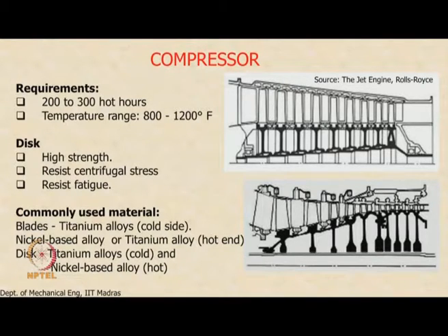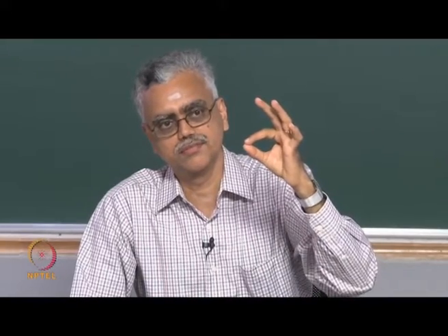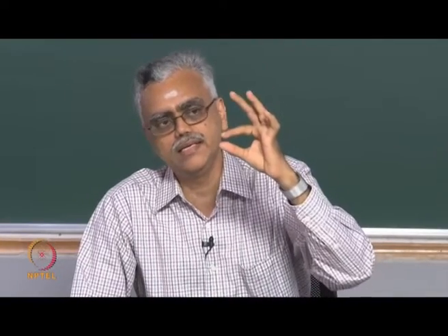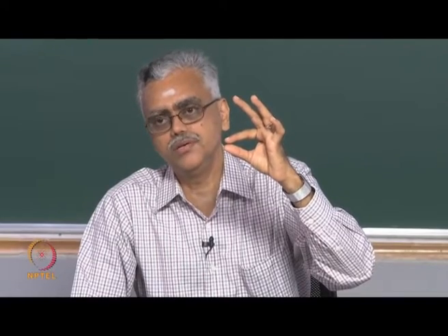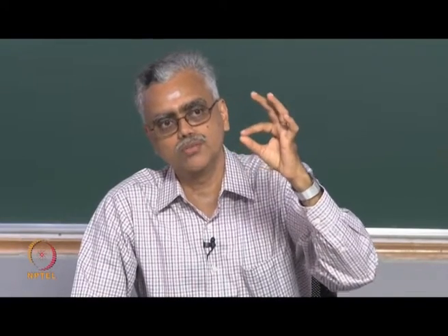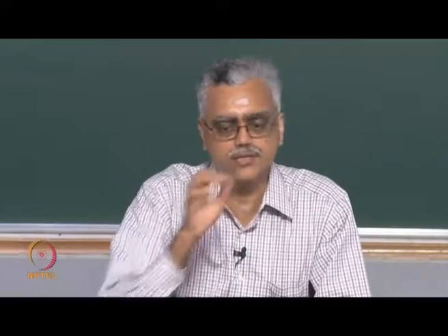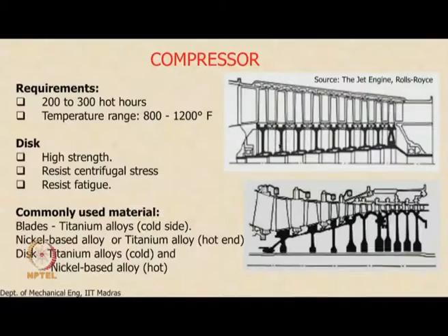Right. So, we want the air to flow through the blade passage and not over the blades, which means the gap must be very, very small, and the challenge is how do we maintain this gap under all operating conditions, and how do we maintain the gap at the desired value throughout. That is probably one of the most challenging aspects of manufacturing this engine, and that is where the hollow regions in this compressor casing come into use, right.